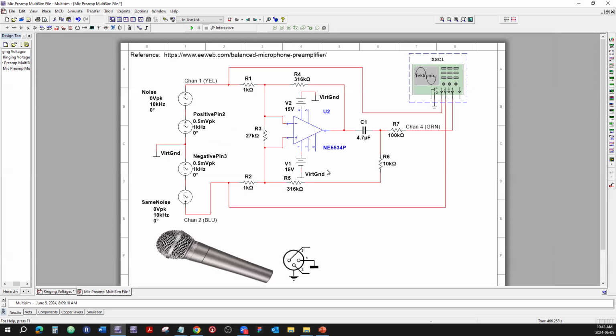Remember when I was talking to you about balanced and unbalanced signal? Here is how a balanced signal works. The idea is that over a longer distance, if you have a weak signal, the longer the distance, the more susceptible the cable carrying that signal is to outside noise, like if a car drives by, or some equipment kicks in, or somebody turns on the vacuum cleaner or something like that, right?